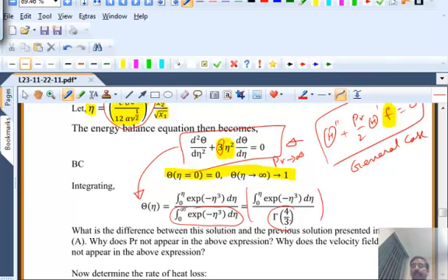Okay, I think we are almost out of time. So that's the temperature profile that we could get analytically in both cases. In both cases, we need to evaluate a quadrature, but in the first case, there are two integrals embedded one inside the other that we need to evaluate. Here, there's only one integral because we use a known profile. We're going to take this in the next class and get what the Nusselt number is from this. Because once you know the temperature profile, you can take the gradient of the temperature profile to calculate the heat flux, and then you can convert that into Nusselt number. So let's just stop there.